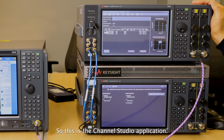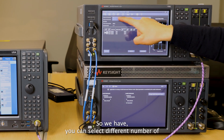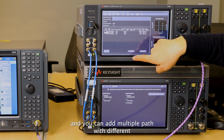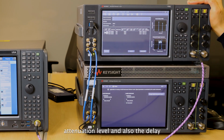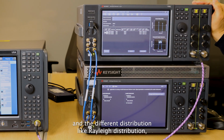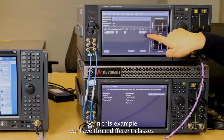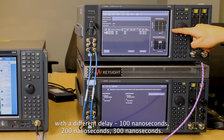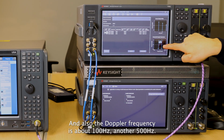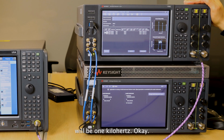So this is the Channel Studio application. We already have a pre-configured profile. So you can select the different number of transmitter antennas and receiver antennas here. And you can add multiple paths with a different attenuation level and also the delay and the different distribution, like a Rayleigh distribution, Rice distribution, and also the different Doppler frequency. So in this example, we have 3 different paths with a different delay, like 100 nanoseconds, 200 nanoseconds, 300 nanoseconds. And also the Doppler frequency is 100 hertz, 500 hertz. And the Doppler spread will be 1 kilohertz.